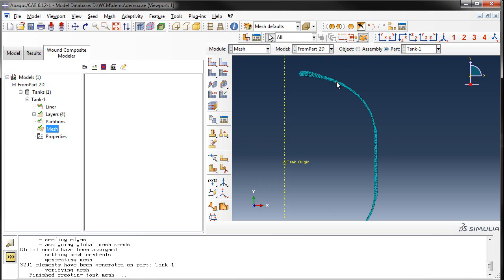The reason we can generate a 2D model, an axisymmetric model, is that when these bands are put down, they're basically woven. So one band is put down, it comes around the back of the tank and comes back at the same angle, but now it's at an opposite angle, so it's like 5 degrees and -5.